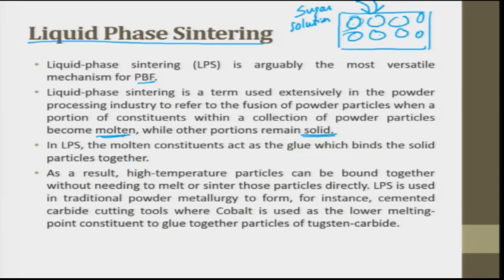So here you don't have to worry about melting the nut even, because all you have to do is melt the coating layer, whatever is there. The coating will always melt at very low temperatures, maybe 700, 800, 900 degrees Celsius. So all you have to do is take a low power laser and quickly do the sintering process. And this liquid, when it melts, tries to fill up all the pores. So the porosity also will be reduced as much as possible. It's a very advantageous process, and today people talk more of liquid phase sintering.